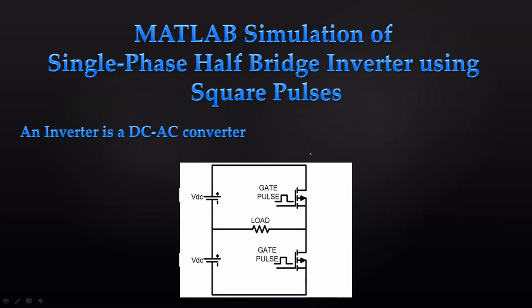So this is a diagram of a single phase half bridge inverter using square pulses, right? The total value of the voltage across this is 2 VDC, right? And the voltage across the load that we will get would be VAC, right? So what is the value of this VAC? We will see. So now these are the gate pulses with 50% duty cycle.